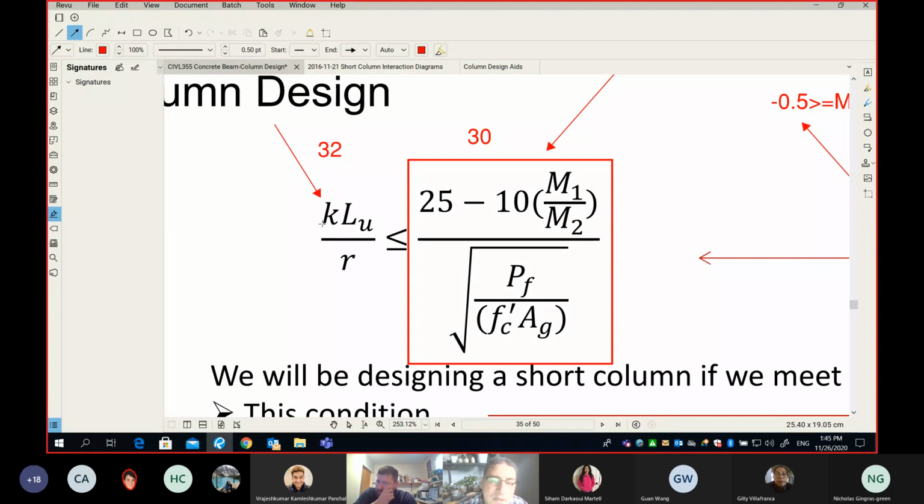So that's one thing. The other thing is, change the floor height, because L unsupported, this number here, you will see shortly, is a function of the floor height. The taller the floor, the bigger L unsupported will be. So somebody comes to you and says, build for me a building with 8 feet or 7 feet floor height. Tell them, no, no, no, I will make it 6. What do you think? Is that feasible?